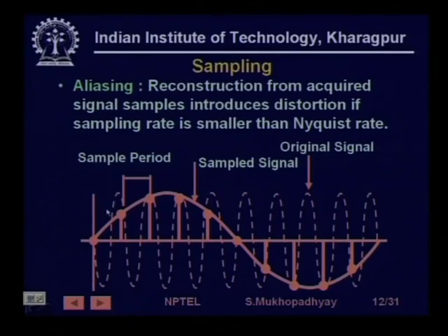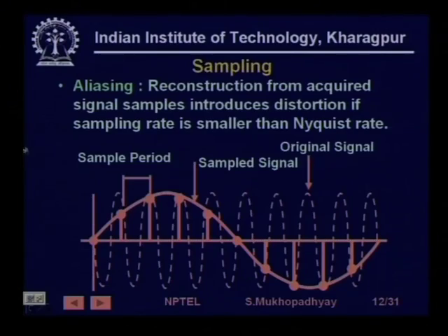So, that is what happens. One frequency appears as another frequency, and that is called aliasing. So, therefore, what do you do? Now this leads to a concept. What you do is you actually need to restrict. You have a certain sampling rate which is fixed, you cannot change that, and you do not know what frequency components are actually present in the analog signal.